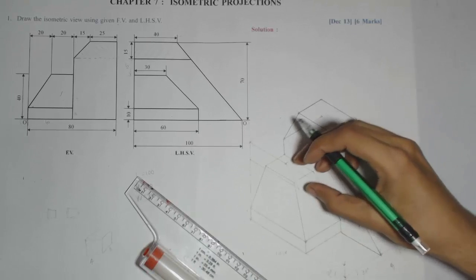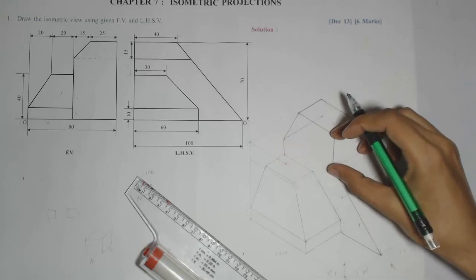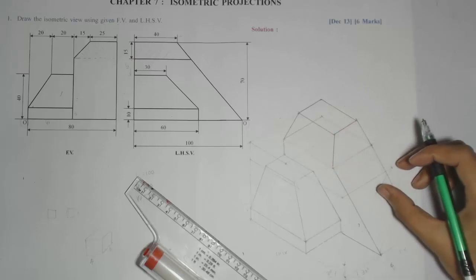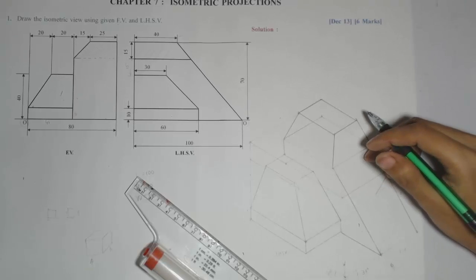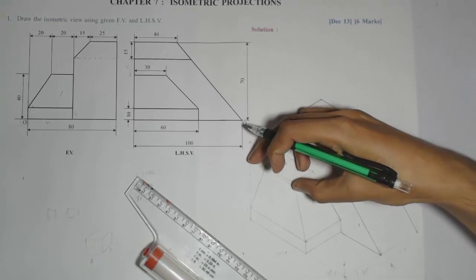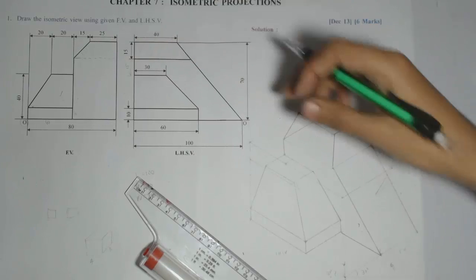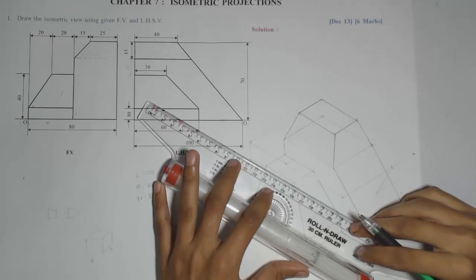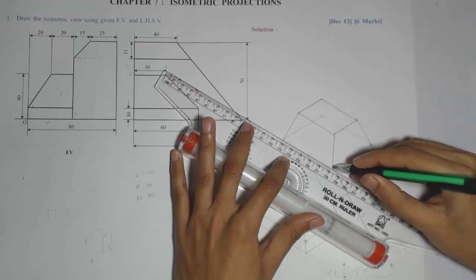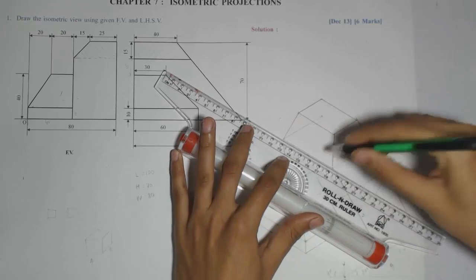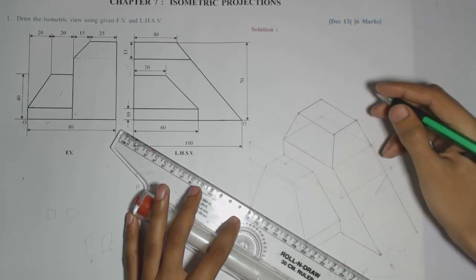Similarly for this line I'm getting this side of the trapezium as an inclined line in side view, and for this inclined line I'm getting this line as an apparent view in front view. Now after completing this, if you see, this base, this line, is visible in the left hand side view. So I'll shift this line from here along the width, and that will be visible. That means from the bottom base, out of these four lines, this line will be visible, which we have not made initially dark.